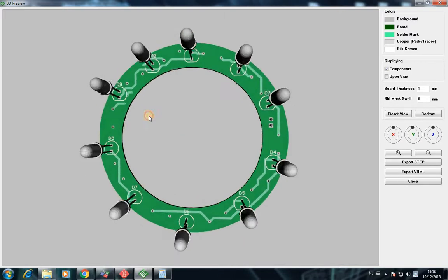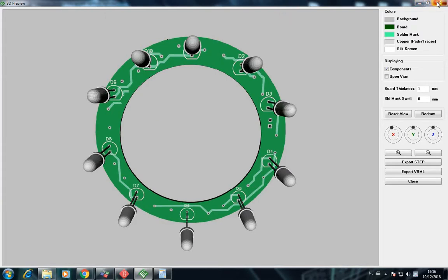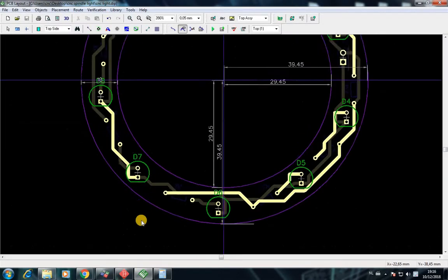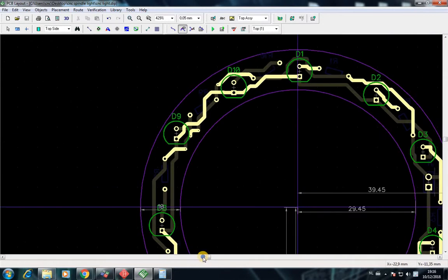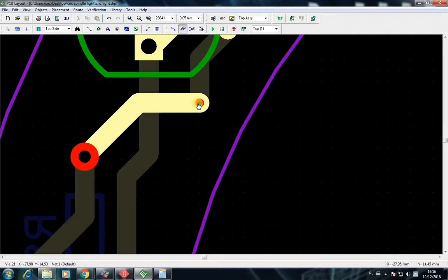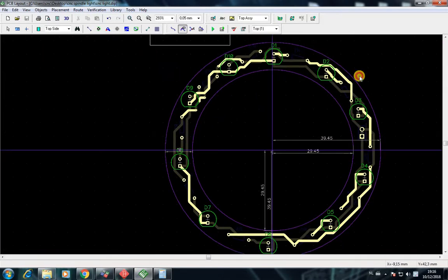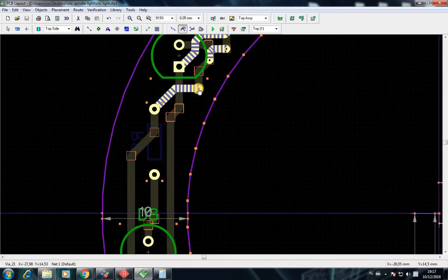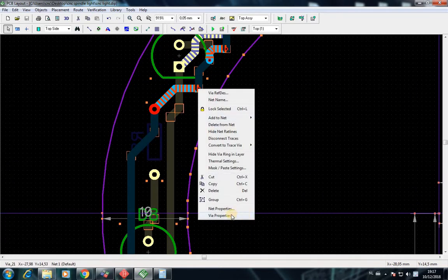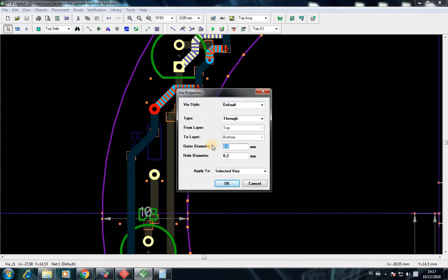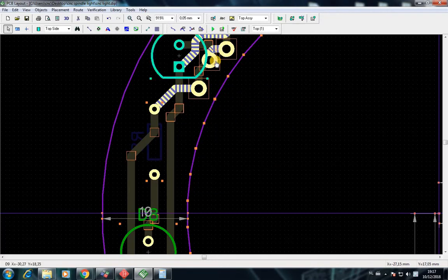It's nice and neat. So I'm going to change the pads over here, because some of them are very small, and since I'm using my CNC machine to do all this stuff, some of the pins are just going to be too small, like this section here. These are too small, so I'm going to try to select everything, move in here, and try to change this if it's possible. Well, I'll take 1 millimeter, that is good. Yes. And then you go.